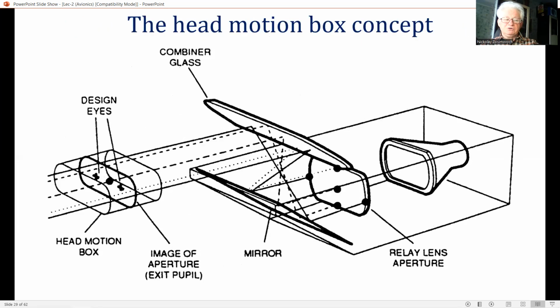This type of HUD is sometimes referred to as a projected porthole HUD, and the image is what is known as pupil forming. The displayed imagery can, in fact, only be seen within the head motion box. If the eyes or head move outside a three-dimensional box set in space around the pilot's normal head position, then the display fades out.